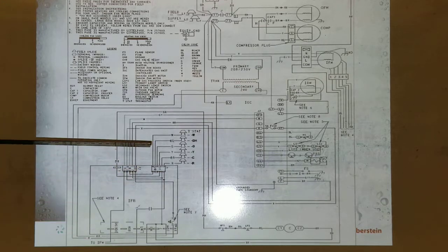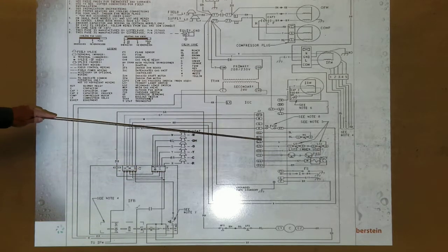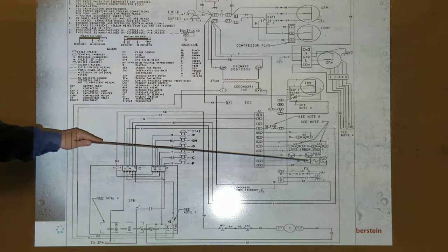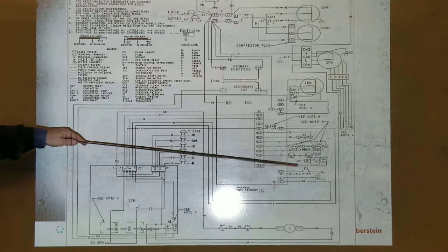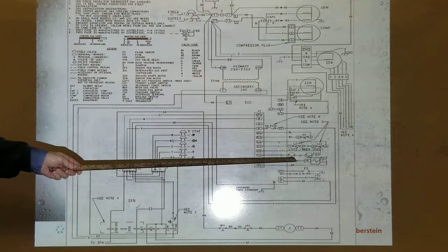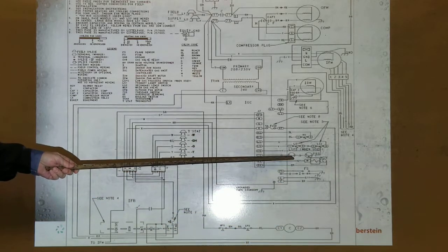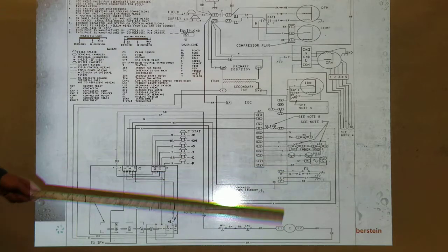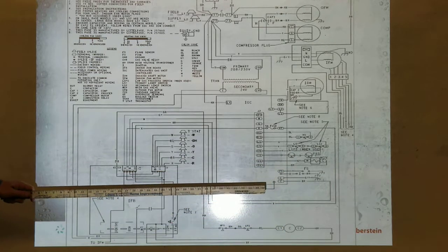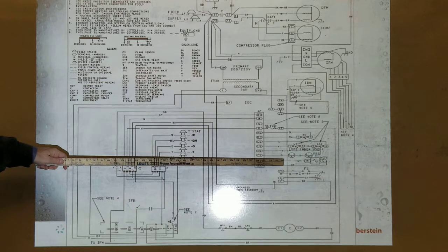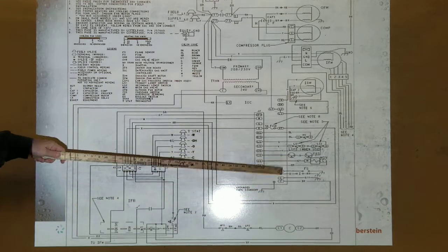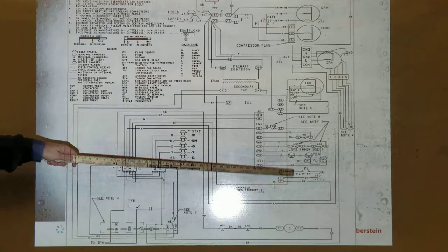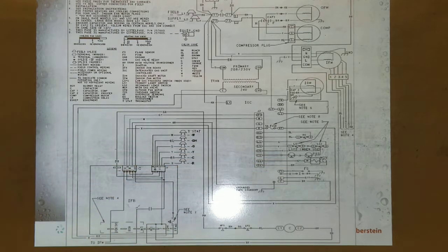And again, the PowerPoint started out with knowing what those controls look like, and identifying them is what's gonna help you, because you're gonna go, oh, look, that switch right there might be open. Well, what is that switch? It looks like a pressure switch. Yeah, a low pressure switch, right? You gotta know what that looks like in order to test it.